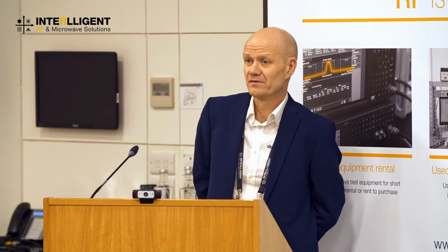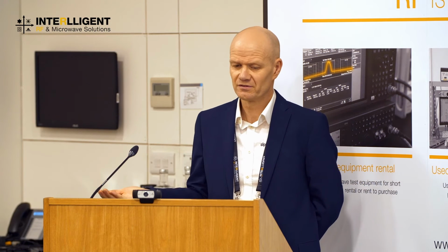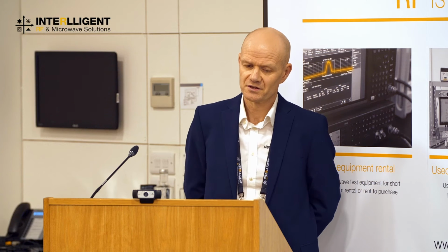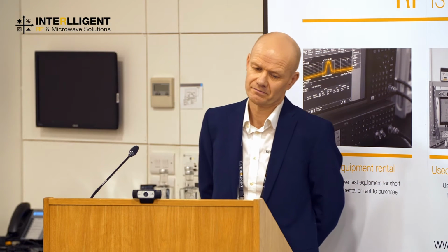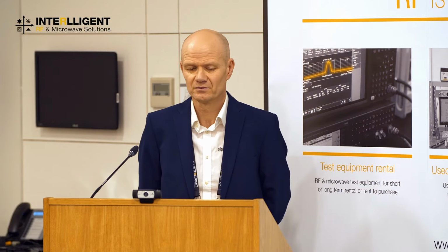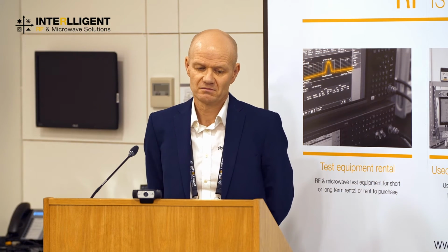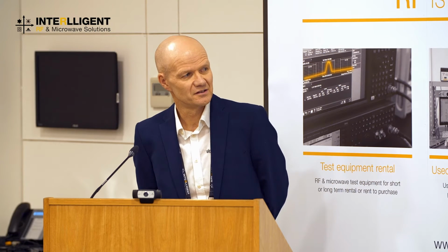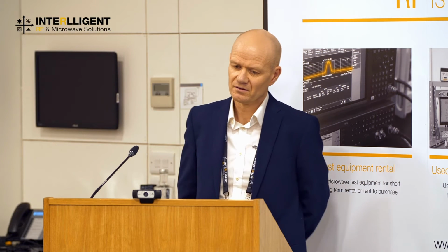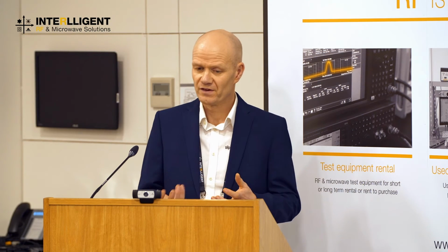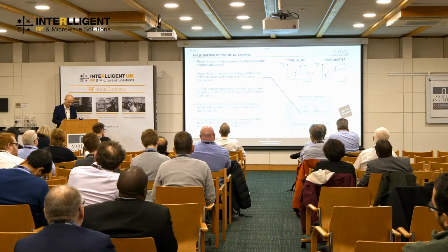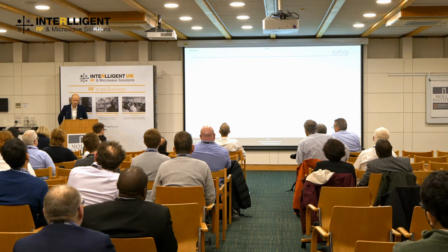So if we're using narrowband signals, it's totally fine to update the phase shift when we change frequency of operation. That's no problem. But the problem comes if we use signals with wide instantaneous bandwidth, such as an OFDM signal, which contains many frequencies. Maybe it could have an instantaneous bandwidth of hundreds of megahertz. So it's not possible to update the required phase shift at that kind of rate. So time delay is what we would like.